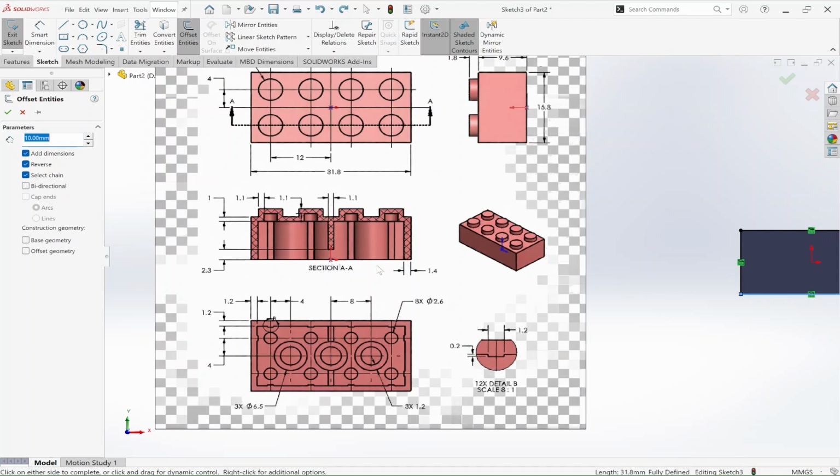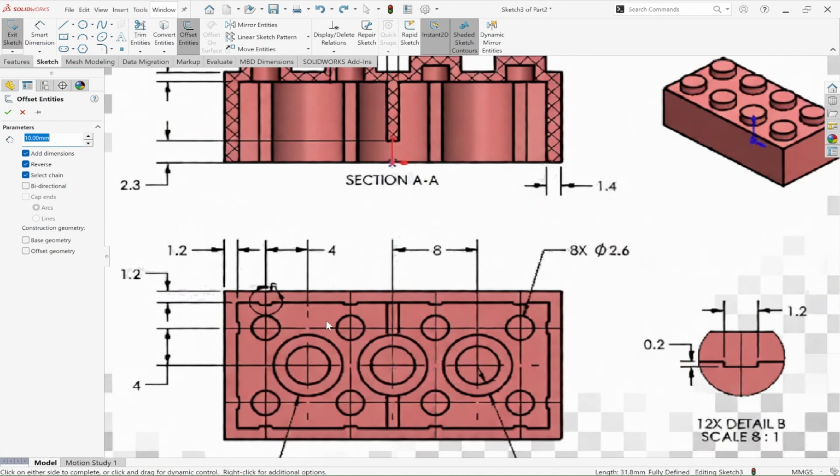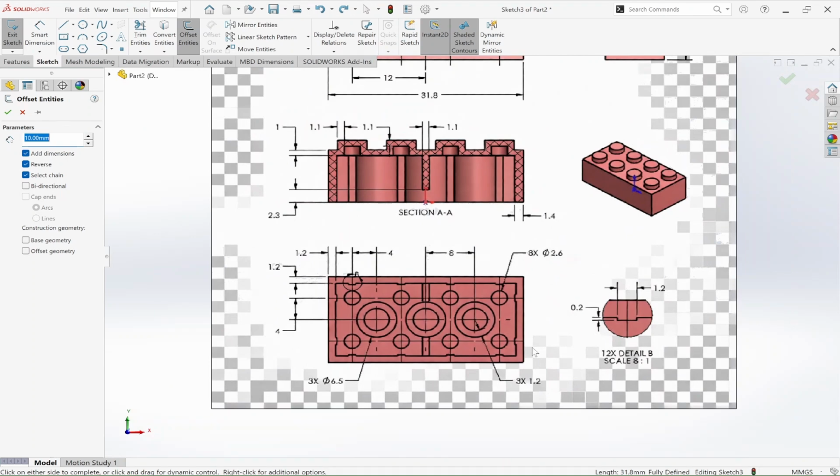I'll tell you because here they have these smaller extra cutouts, to increase the clearance between two pieces. So whenever we push into the other piece, it should remain intact and not lose easily. That's why we have given these extra cutouts. So they have considered that cutout and added it in the wall thickness. That's why they have mentioned 1.4 mm.